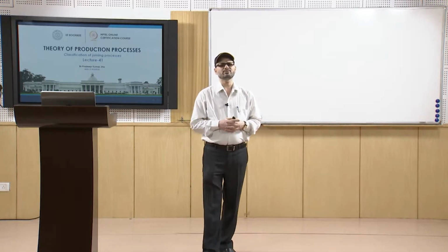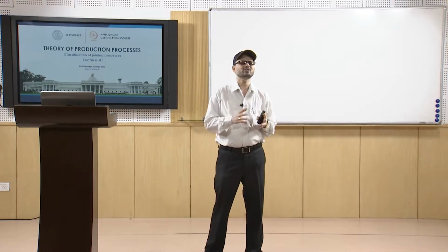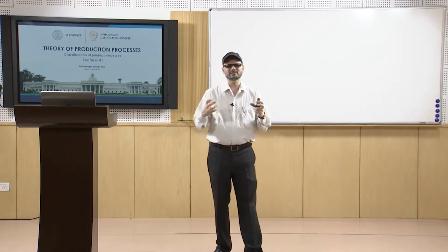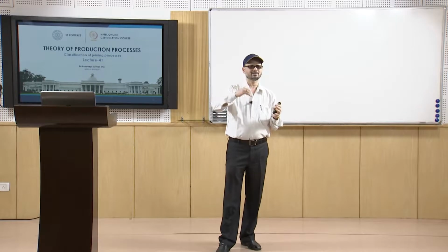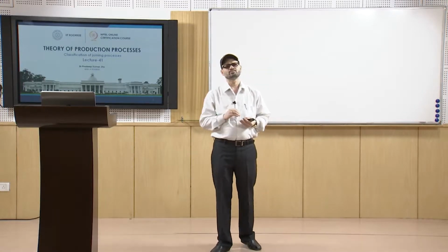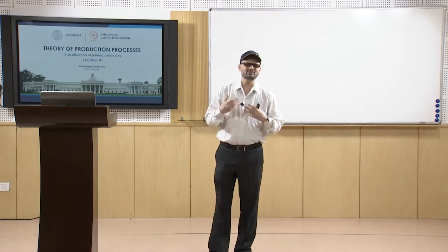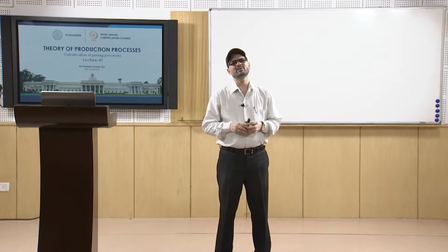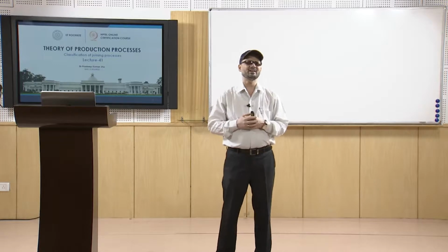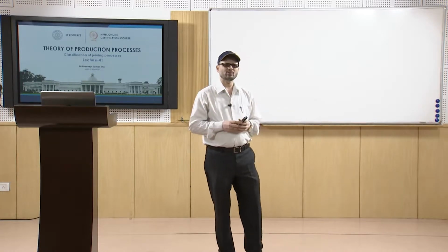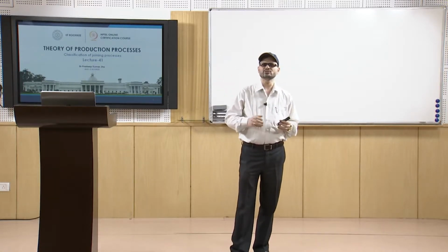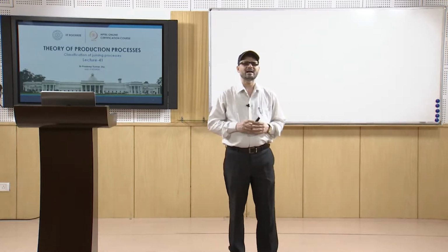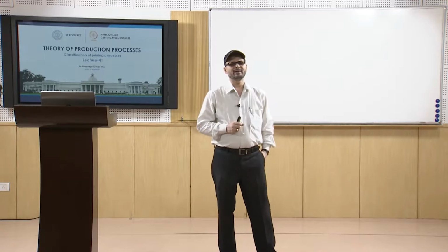All types of solid phase welding and resistance welding come under that. Basically you have two pieces and you do not use any external filler material to add. You must have the idea about the filler materials and parent material in welding. So, in the case of autogenous you do not use these filler materials during that joining. Then you have